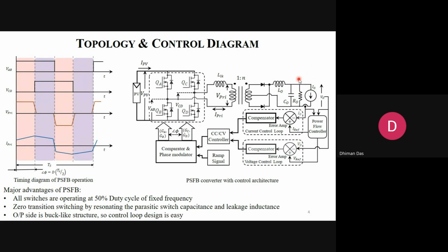When the battery is initially discharged, you can quickly pump the current using CC mode, and when it reaches a certain voltage level after charging, then you can operate in CV mode, because in CV mode the current limitation is no longer there. You can just push a small amount of current to raise up the voltage.